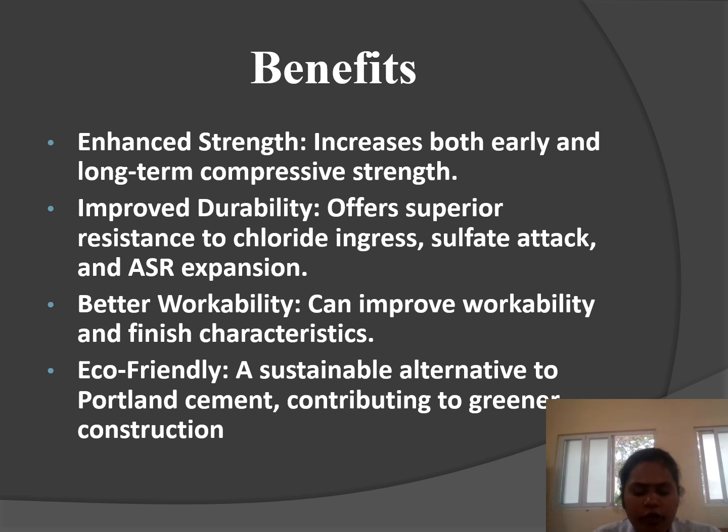Benefits of metakaolin: enhanced strength, increasing both early and long-term compressive strength. Improved durability: it offers superior resistance to chloride, sulfate attack and ASR expansion. Better workability: it can improve workability and finish characteristics. Eco-friendly: a sustainable alternative to Portland cement, contributing to green construction.